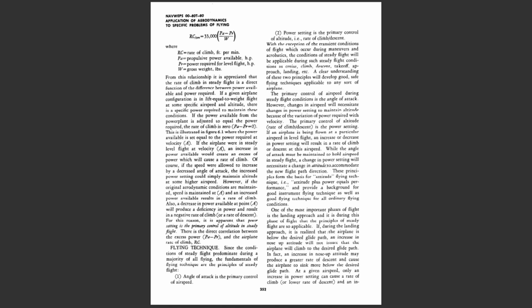While the angle of attack must be maintained to hold airspeed in steady flight, a change in power setting will necessitate a change in attitude to accommodate the new flight path direction. These principles form the basis for attitude flying technique, i.e., attitude plus power equals performance, and provide a background for good instrument flying technique, as well as good flying technique for all ordinary flying conditions.